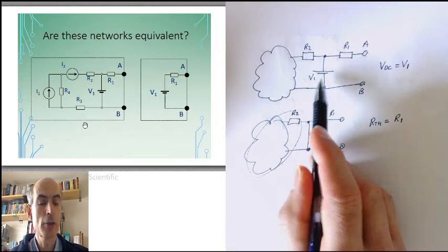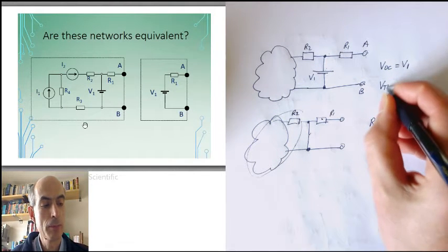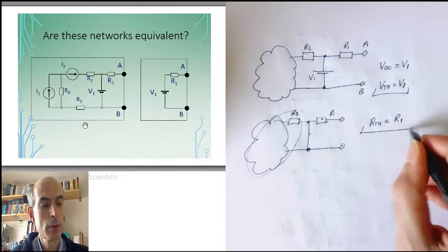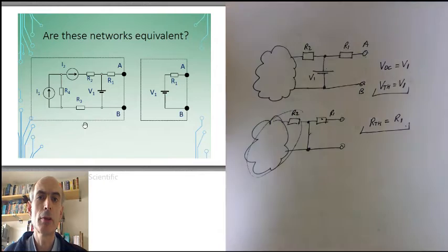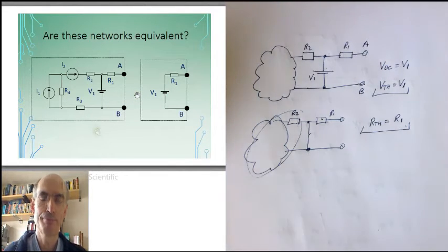And since the Thevenin equivalent voltage is the open circuit voltage, we can derive our Thevenin equivalent network here just by examining V1, R1 and all of these components. The two current sources, resistors R2, R3 and R4, make no difference at all.